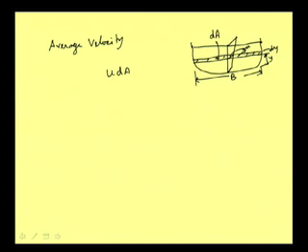That will give us the discharge, and as this is varying, we can write the integration of this over the entire area. This will give us the total discharge Q. But of course, here we know that in our case dA is nothing but B into dy. So B into dy, this width is suppose B, so B into dy is the area. Okay.